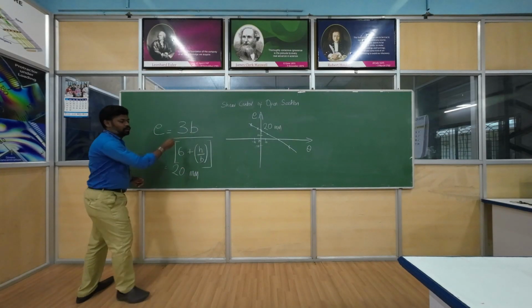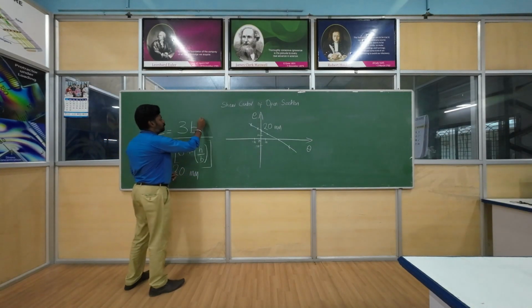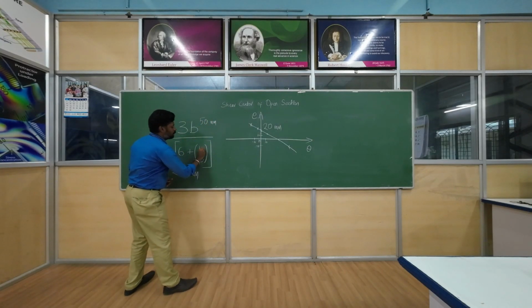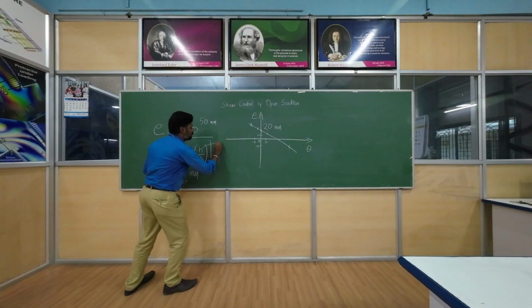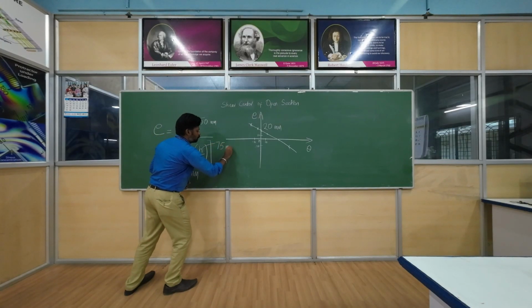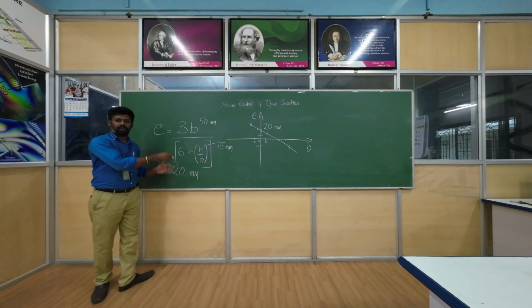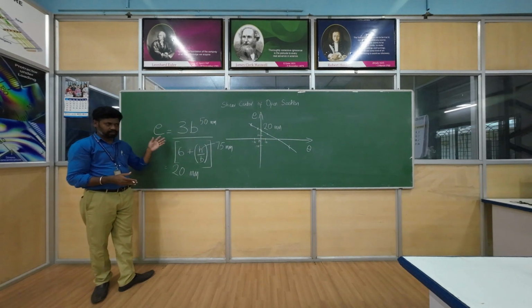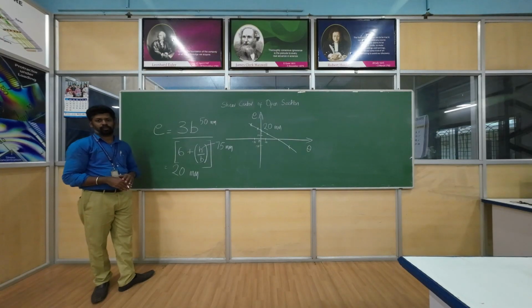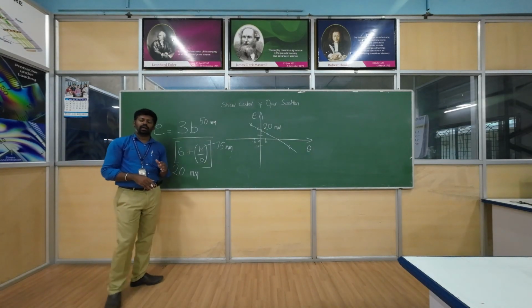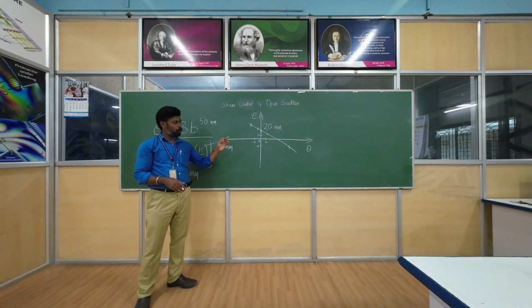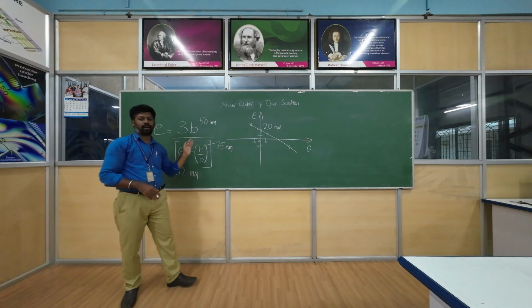So we know the width of the flange is, I think, 50 mm, and we know the height of the web is 75 mm. So for this geometry, for this dimension, the shear center of this section is 20 mm. So by this way, we can determine the shear center of the channel section both experimentally and theoretically.